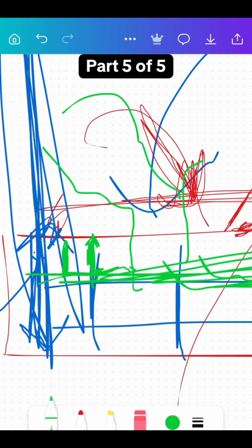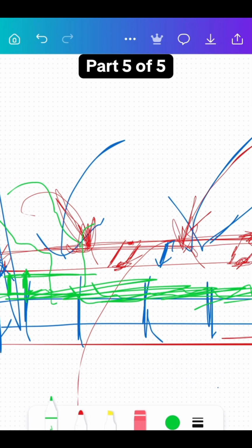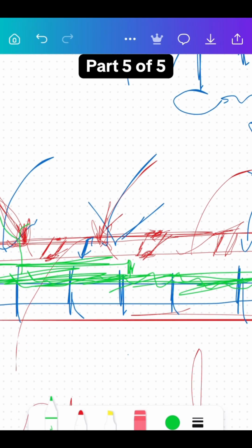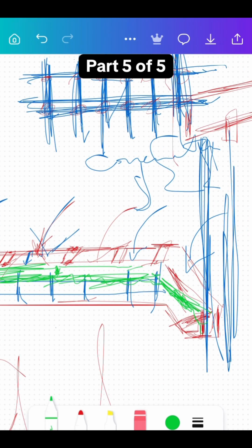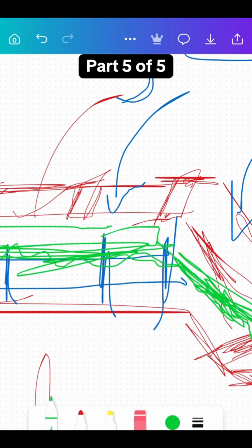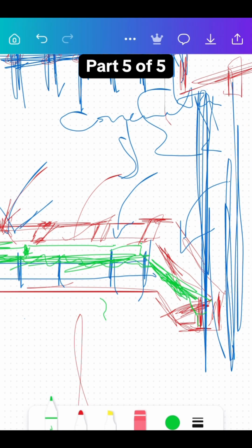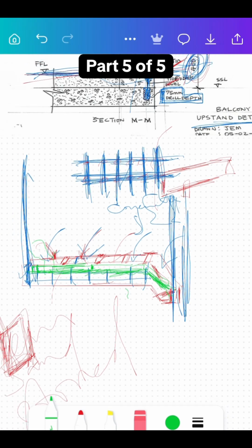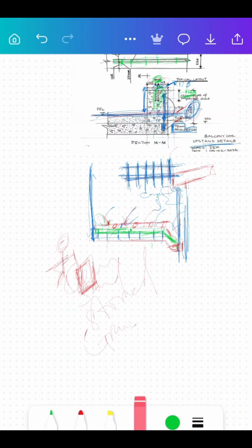On top of what we've casted, we've poured some concrete, we'll place the polystyrene sheet. Sometimes they're not long enough, so we usually use nails. We'll put another one again, side by side. We'll attach it, hold it with nails. We'll put another one. This joint is all off. Then we'll put another polystyrene sheet again. So let me just clear all these things up.